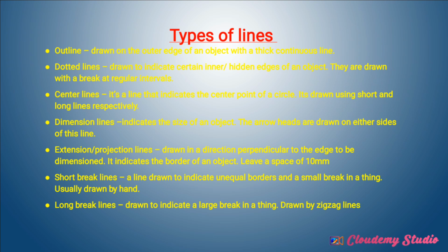From there is a note that I have given you that in case you are told to dimension, there is a question you can be asked: copy the image below and insert 5 major dimensions. As you draw that picture, when you are doing the dimensions, you'll have to first draw the projection lines to show the extent or the limits of the length. Then after you have done that, from the object you'll have to leave a space of 10 millimeters, which is equivalent to 1 centimeter. Then you draw your dimension line.